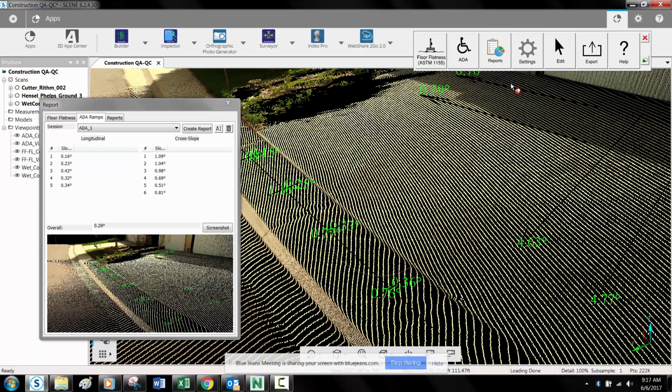I believe 2 degrees or 2.5 degrees is the ADA compliant cross slope for sidewalks. Let me take a note here so I can get that exact number and email it to everyone, so we're not talking about wrong cross slopes when the ADA conversation comes up.